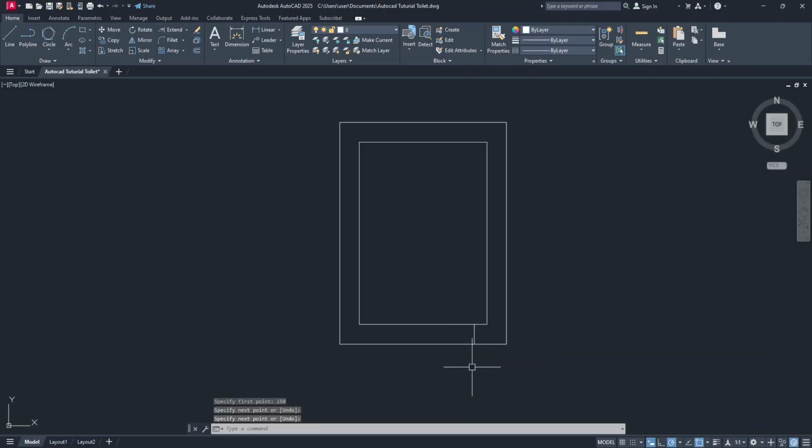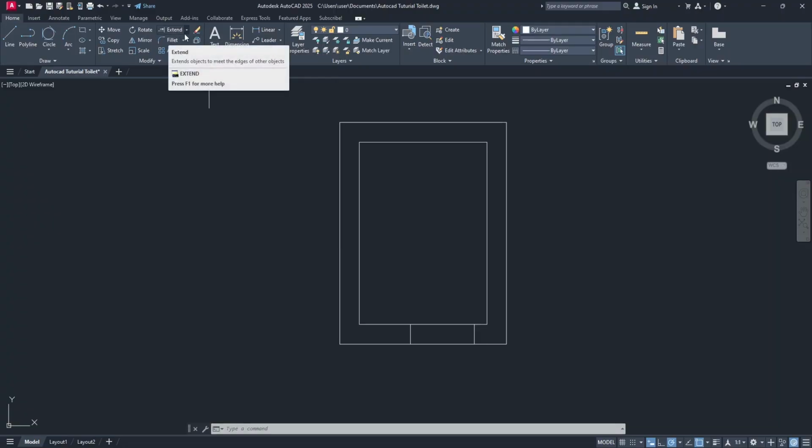Click, press enter on your keyboard. Select offset, type a distance of 750 and then press enter. For inches, just type 30, no symbol. Click once, point to this direction and just click. Press the escape key. Now to cut the opening, it's not erase, it's trim.